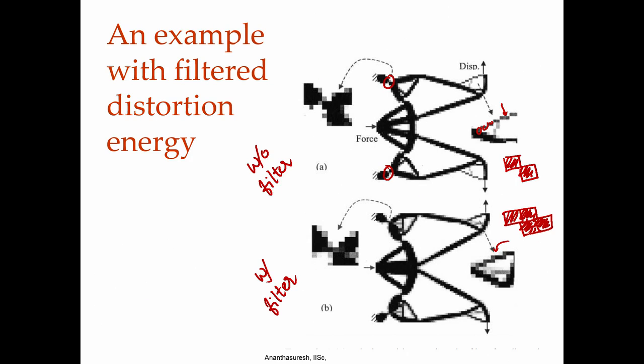In fact, because of this, some others, in particular Professor Anupam Saxena, IIT Kanpur, have extensively worked on what he calls hex elements. You discretize your structure not with square elements, but with hexagonal elements, and each hexagon you divide into 2 quadrilaterals. So, each of these is now a finite element quadrilateral.